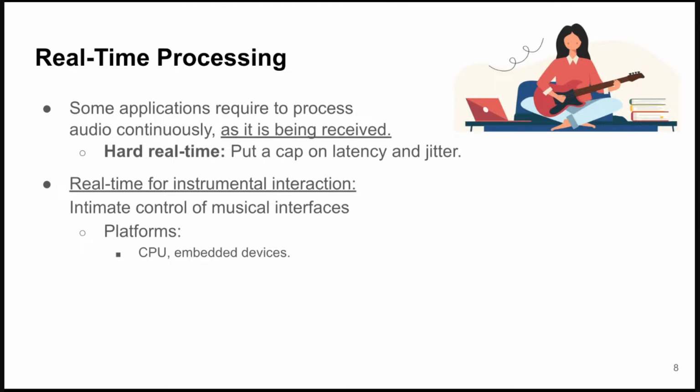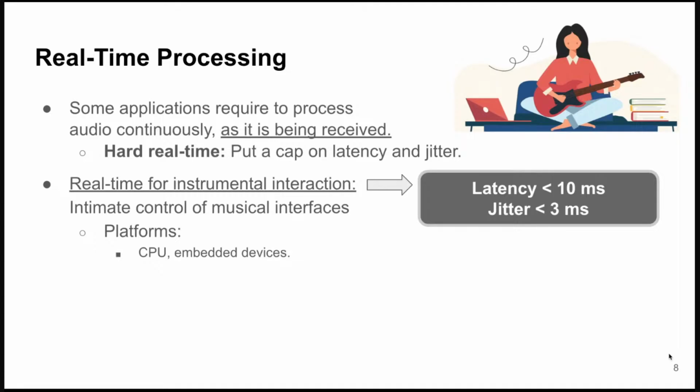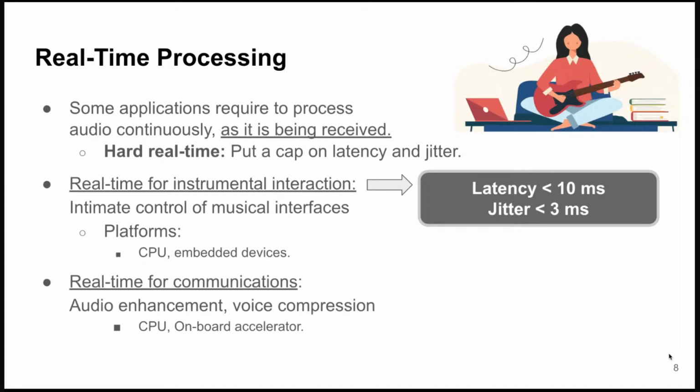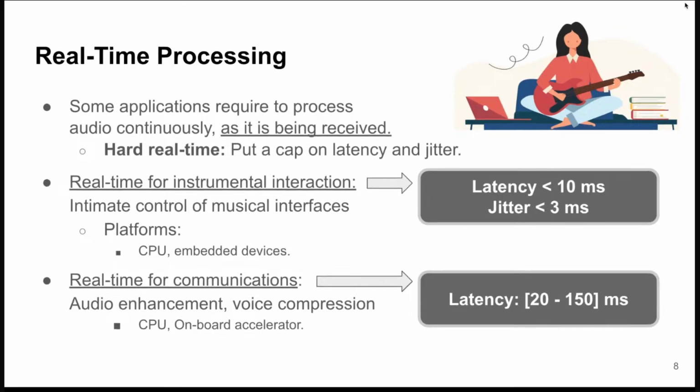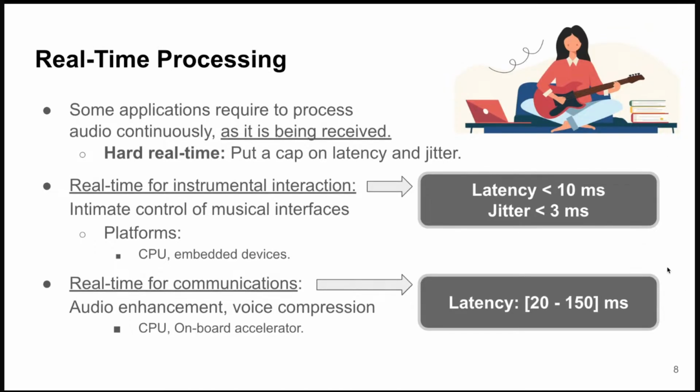There are also some other applications you might want to use. For example, if you're doing a communications application, then maybe you can get away with a bit more. If you're doing echo suppression or some kind of voice enhancement, you're in a conversational setting: you talk, the other person hears you, and they respond. If there are a few more milliseconds of latency in that exchange, it's not such a bad thing, and it doesn't really disrupt the flow too much. Once it gets longer than maybe 150 or 200 milliseconds, you'd probably notice it and it'll disrupt your flow a little bit. But you have more wiggle room than in the music case.